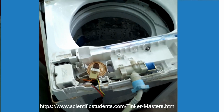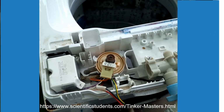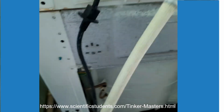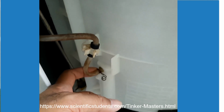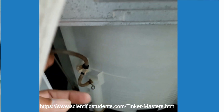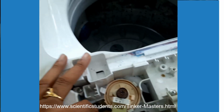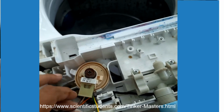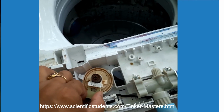So after making it rework, I'll show you whatever I do about it. Okay, so I'll start from this particular drain out. The sense point gives a pressure here. That has come here, and from there it has to give a signal at what water level through the pressure. Okay, so I can check it by blowing water into that.